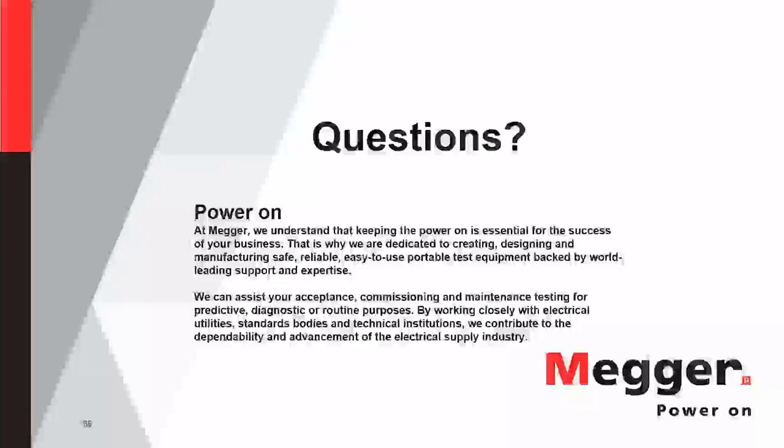If you're really worried about your arcing contacts and the pitting and the bad connection, this is why you would do that thing we mentioned earlier called the dynamic resistance measurement test on your SF6 circuit breakers, because you'll see that arcing contact shrink, and if the resistance value is going up, you can compare to previous measurements and see that something's going on, and that arcing contact is wearing away prematurely, I would say.